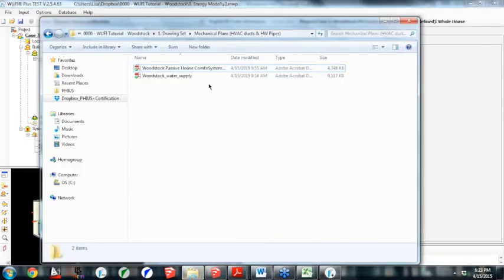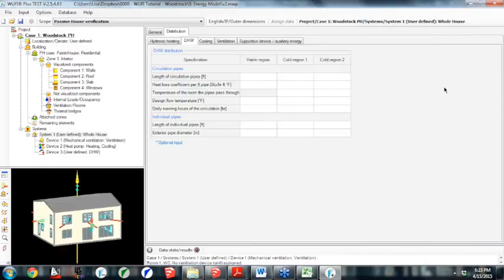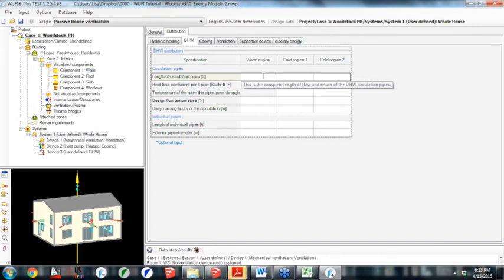One thing to note is a lot of people think circulation pipes mean something like on-demand recirculation, which is getting pretty popular, but it's actually not. It's something that's more so seen in commercial or maybe larger multifamily buildings where there's actually hot water circulating for X hours per day, no matter what. It's not an on-demand system. It's just a constant recirculation system. So if you have an on-demand system, you do not input this as circulation pipes. So we're going to breeze over those 2. We don't need those 2 because we don't have a circulation system.